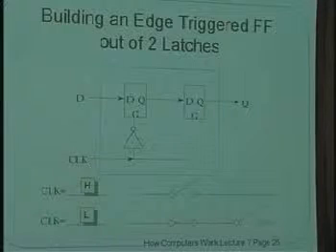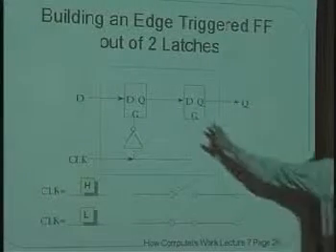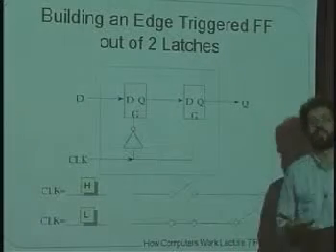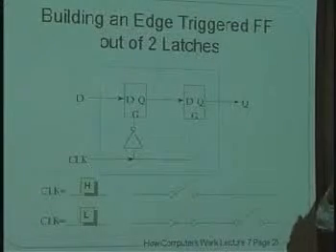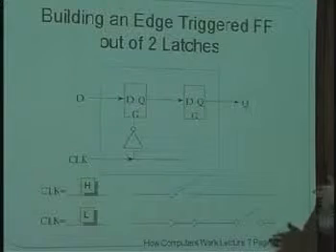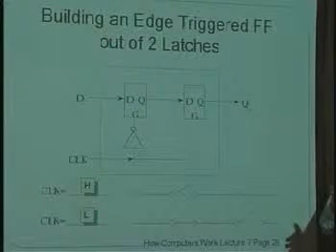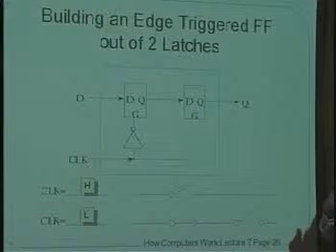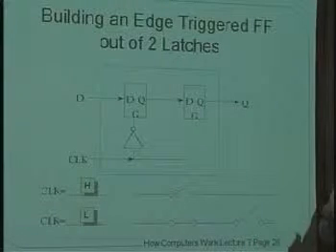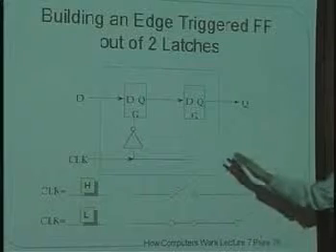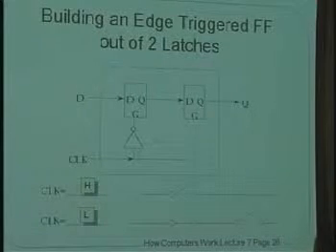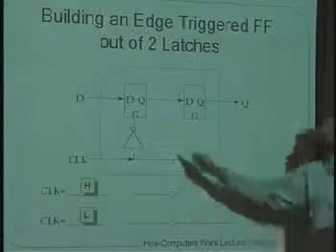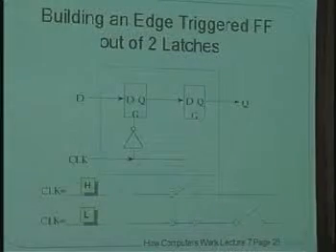There's another style of clocking where you sort of make sure one of these goes off before the other one goes on, as you would in an airlock, okay? If you have these two doors, right, and one's going to open when the other one is going to close, what you really want to do is close both of them and then open the other one, close that one, and then open the other one, close that one. And so the design of the circuits on the inside, the designers are very careful to arrange the timing in such a way that it is never the case that both of the G's are high at the same time.